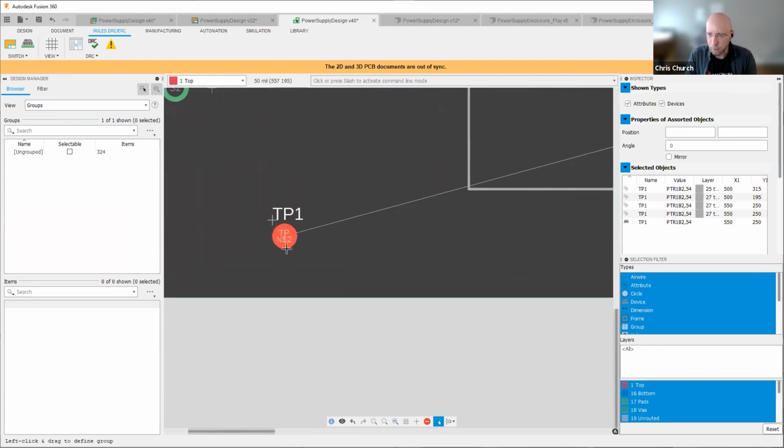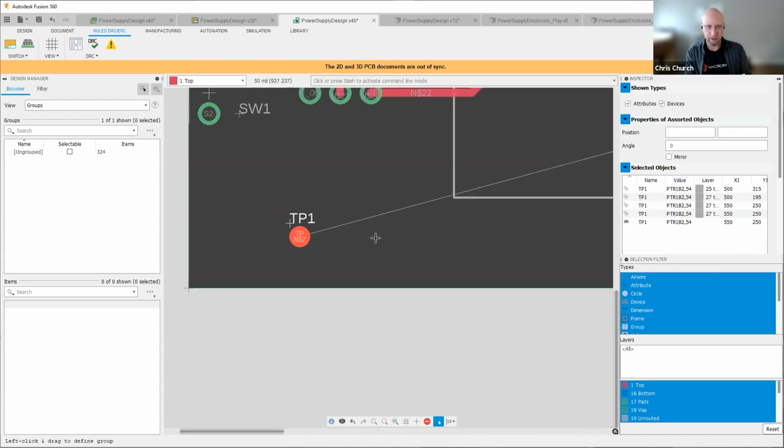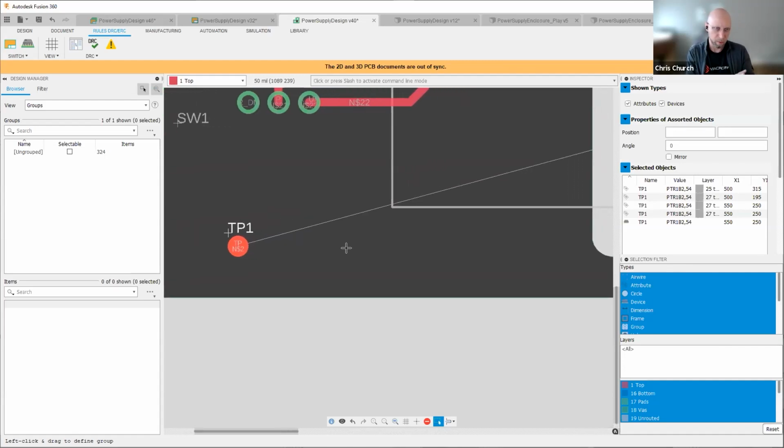The other question there, would MacroFab suggest design improvements, dimensional increases to pads and anti-pads to reduce the effects of drill wander? We can. Typically, our design rules keep you within spec of that drill wander we're looking for. I think in our previous webinar, we talked about annular rings and a lot of the rules around those.